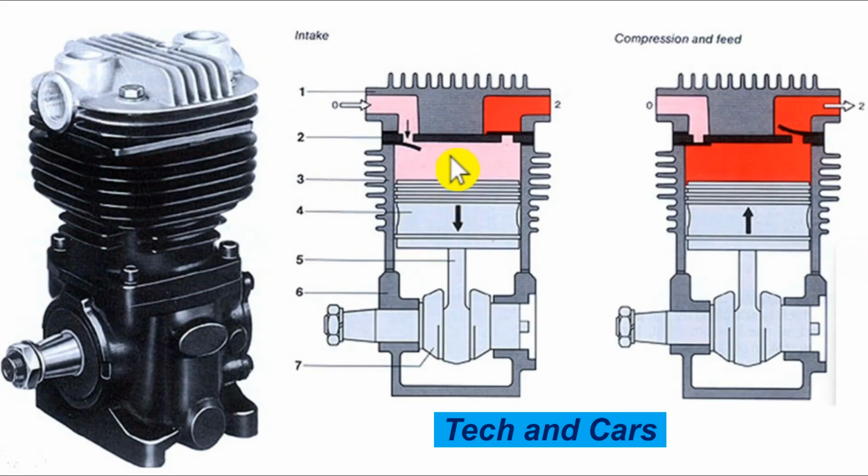The pistons that are used inside this air compressor are just like normal engine pistons, with piston rings and a connecting rod connected, and they need lubrication for longevity and operation. If you find that the compressor is losing its efficiency and not compressing as much, it more probably has to do with wear of the piston rings or the cylinder itself.